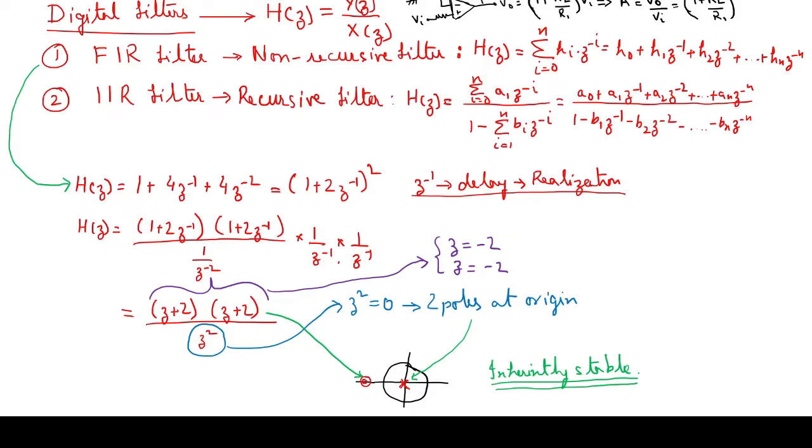So before coming to H(z), let us take the example of a non-inverting amplifier. I hope everyone knows what a non-inverting amplifier is, even the biotech people, right? So this is a non-inverting amplifier. We give Vin, we get Vout, and we have 1 plus R2 by R1 multiplied by Vi as the output.